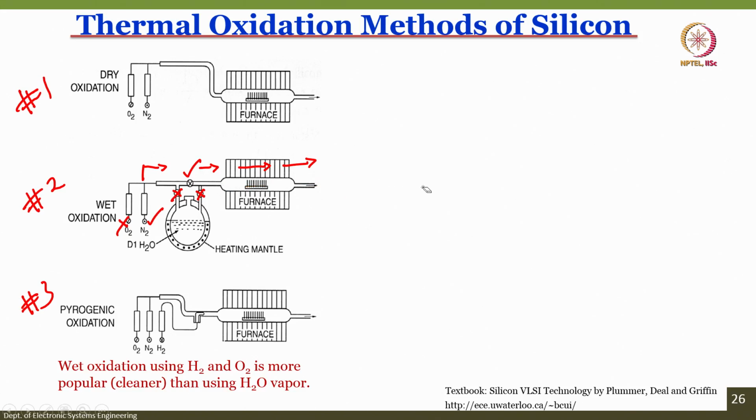Now, where are the silicon wafers? Silicon wafers are placed inside the furnace, and in the presence of nitrogen, the silicon will not form any silicon dioxide. The reason for nitrogen also is to purge, to remove the excess oxygen which may be there in the furnace, because air contains oxygen. So, purging the air out of the furnace is also the role of the nitrogen.